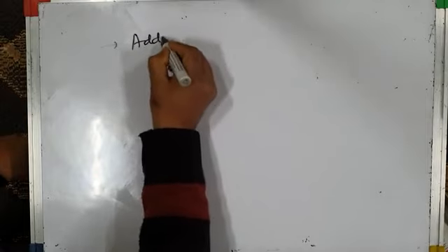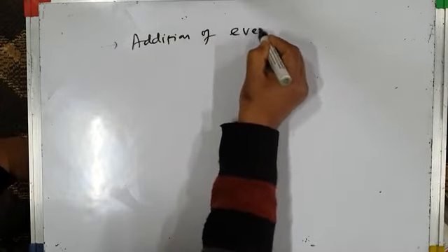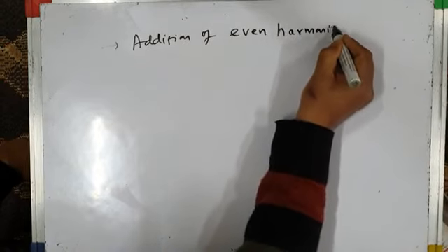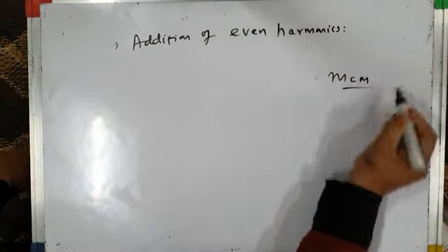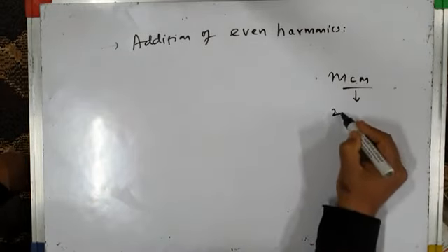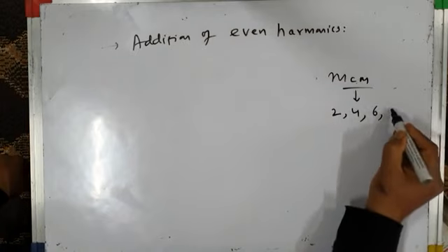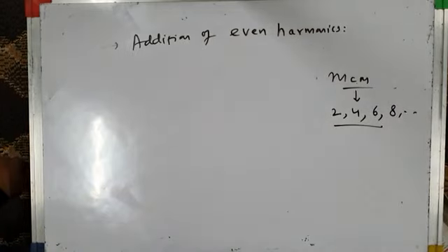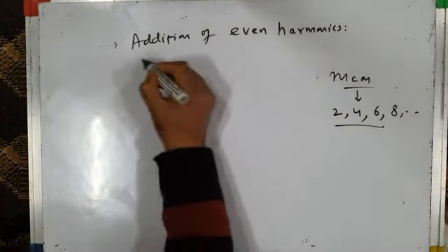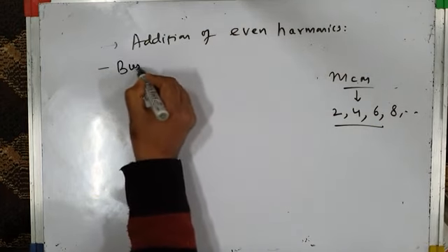Therefore, we can say that the bus clamping technique with equal device loading we achieved by adding even harmonics. The common mode voltage that we added, if you analyze it, will have a second harmonic, fourth harmonic, sixth harmonic, eighth harmonic component. It will not have odd harmonics. So it is an even harmonic wave. It modified our modulating reference waves, and it gave bus clamping. The result is bus clamping